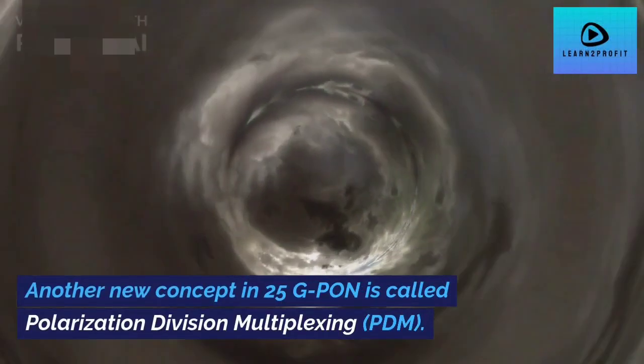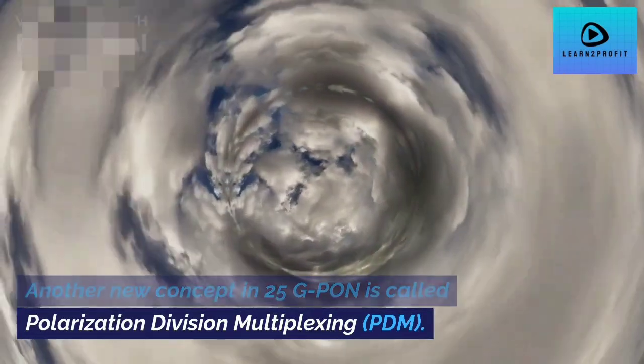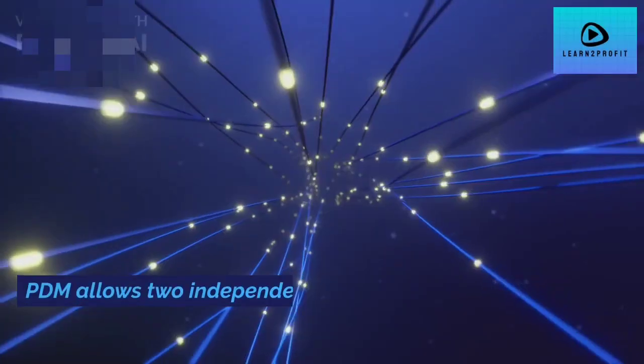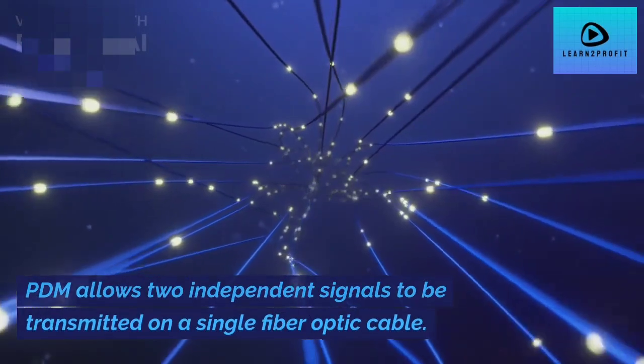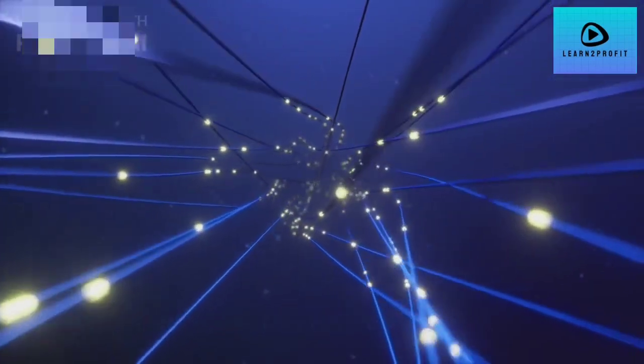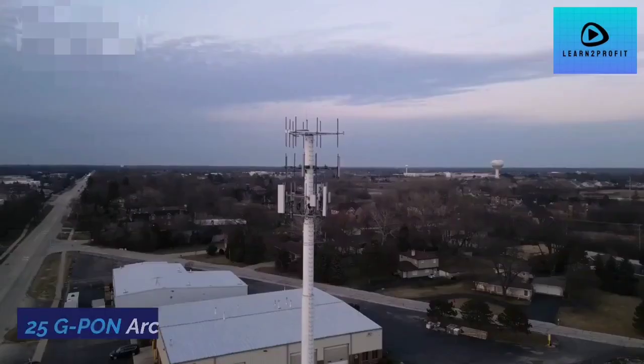Another new concept in 25G PON is called polarization division multiplexing, PDM. PDM allows two independent signals to be transmitted on a single fiber optic cable. This doubles the available bandwidth on a single fiber.